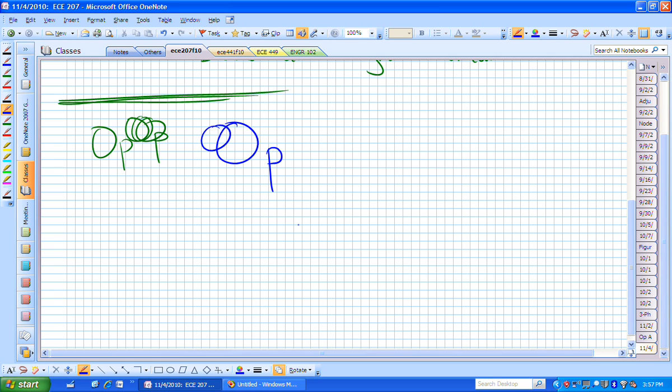If I go up to my circuit, the reason that that drop is plus is I'm assuming a drop from left to right across that resistor. And I'm coming up from here, so that's plus V sub D. You didn't have trouble with that. But now you're wanting to know, why did I say that's plus R sub F? Well, this current I2 is going from left to right, and that's the direction I'm moving in my KVL equation, so that's going to be a plus R sub F I sub 2.